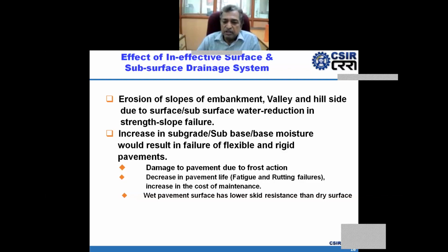It will increase the subgrade and subbase moisture, which will result in the failure of flexible or rigid pavements, damage due to cross sections. It will decrease the pavement life, like rutting or fatigue.